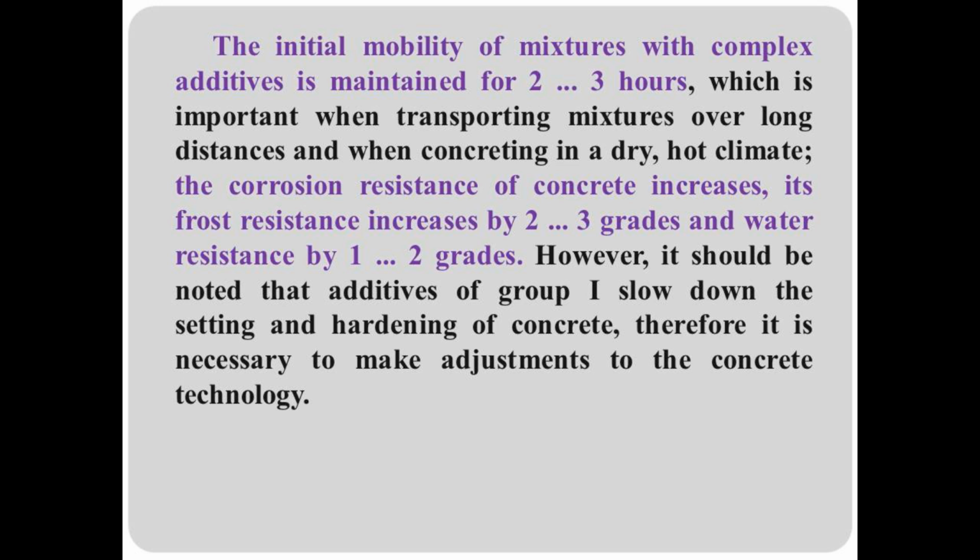The initial mobility of mixtures with complex additives is maintained for 2-3 hours, which is important when transporting mixtures over long distances and when concreting in a dry, hot climate.